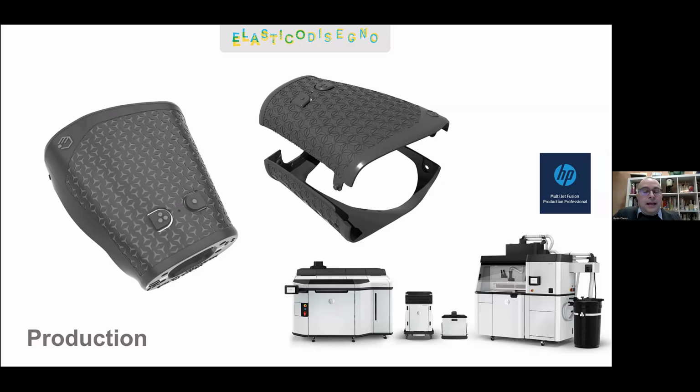This has also allowed Prensilia to periodically receive user feedback from the amputees using this device, and rapidly implement the changes, make adjustments with no impact on tooling, because there's no tooling. The only downside at the time, this was 2019, was that the color options for the 3D printed parts with Jet Fusion printers were quite limited, because the parts come out of the printer in a dark gray color. It can be tinted by immersion, so you can have all variations of gray, dark gray, or black. So not that many options.